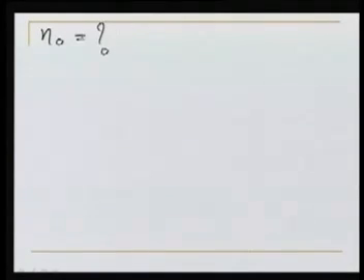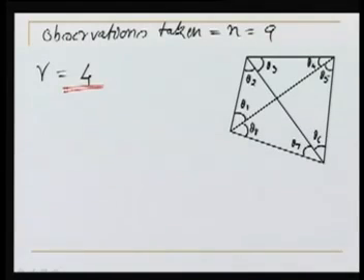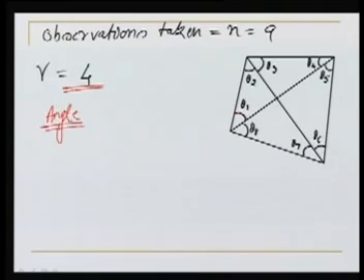Well, so we know now, in this case, n naught was 5, n was 9, r was 4. So we need to form 4 equations, or the 4 condition equations. Now what will these condition equations be here? The condition equations will be, as you can see over here, can we form some angle conditions? Well, let us say, and again, these 4 conditions should be independent. So the first condition equation we can form as theta 1 plus theta 2 is equal to theta 5 plus theta 6.